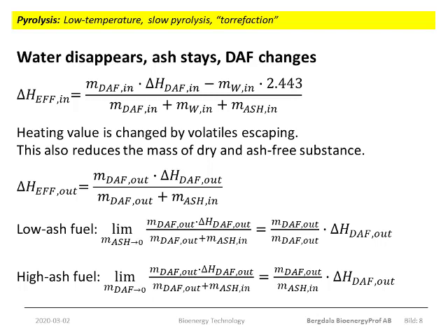There will also be some heavier hydrocarbons called tar that will form and leave the material as a thermal cracking product. But part of this tar, and part of the lighter gases too, will react with a charcoal matrix on its way out through the pores. And this will hold some of the heavier hydrocarbons back so that they stay in the solid phase. This will change the composition of the dry and ash-free substance. It becomes enriched with respect to heavy and high heating value hydrocarbons.